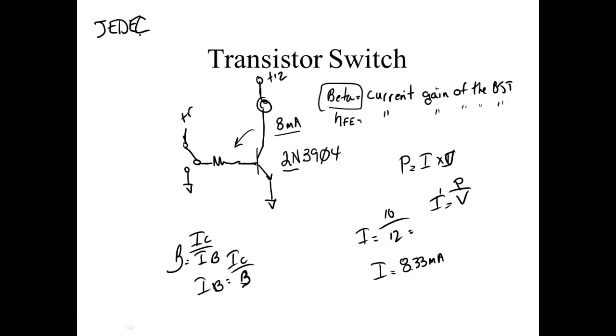And the packages that we put these things in are standardized packages. They're all JEDEC registered packages. So if it's JEDEC registered, it means it's open technology. So that means anybody can use that TO-220 package if their circuit only needs what? 3 pins. And dissipates a certain amount of power.